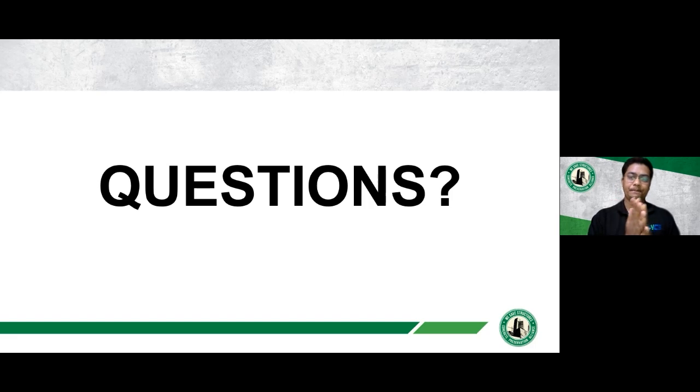From Solomon: can you determine if reinforcement has been corroded by the data collected by GPR? The level of corrosion on the reinforcement cannot be detected by GPR, but there is another non-destructive test called corrosion potential surveys, which can tell you to what extent the rebar has corroded, or the probability of active corrosion happening in the concrete. So no, GPR cannot tell you how much corrosion has happened or the rate of corrosion,